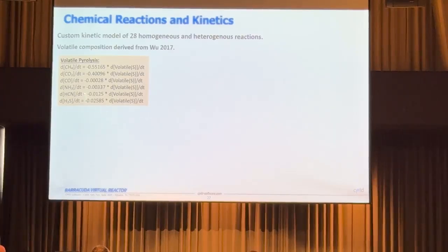Then once it dries down, you have basically the pyrolysis of that feed that happens. So all these pyrolysis gases actually come out of your solid material that you're getting in. So that's actually the first thing that happens when the feed is brought in. And then you get methane, CO2, some nitrogen-based compounds like ammonia and hydrogen cyanide and so on. Right? So this is the first thing that happens.